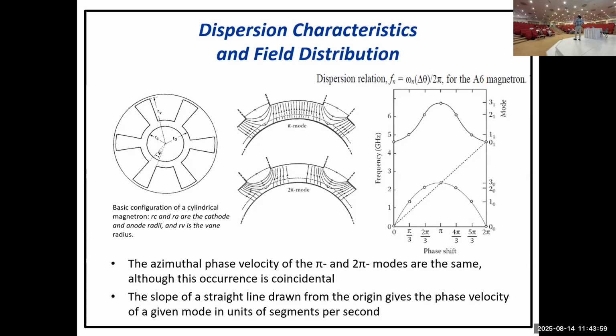I will carry you from the basic waveguide parallel plate setup to once you have corrugations. Yesterday I showed you, if you have two plates, this is a parallel plate, but if one of them has some corrugations, I made this one. These are corrugations of the surface, basically cavities. In a magnetron, they really have more depth than what you see here. But if you twist this around the cathode, this is the cavity, right?